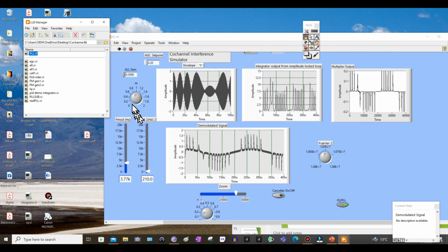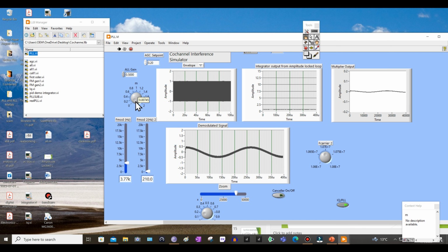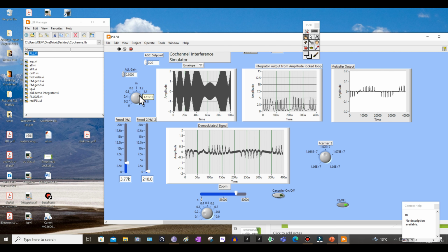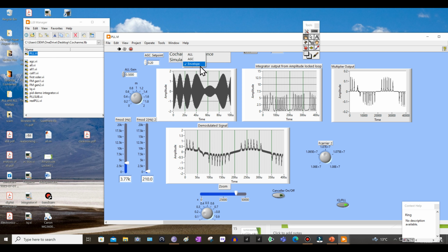We had these spikes. As you get rid of the other carrier, they disappear. As soon as you put the carrier in, there's no signal in the carrier. The spikes get bigger and bigger, and then they sort of flip over in that direction. In the amplitude locked loop, the AGC just scales everything so it's of a suitable amplitude for the amplitude locked loop, because the amplitude locked loop hasn't got a large dynamic range.